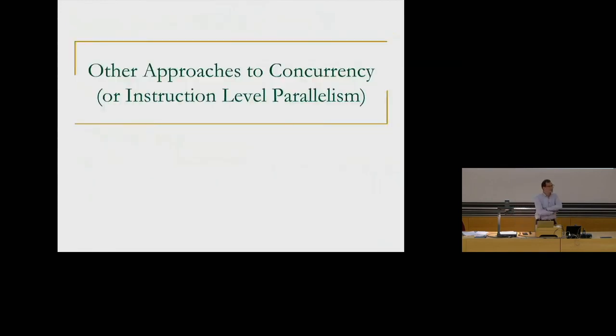Any questions? Is this clear? The complexity? I'm not going to ask you questions on the load store forwarding logic. But you should really know that this is really the tough part. People try to scale the size of the instruction window. Yeah, they can scale the reservation stations, but it's very tough to scale this logic much larger.